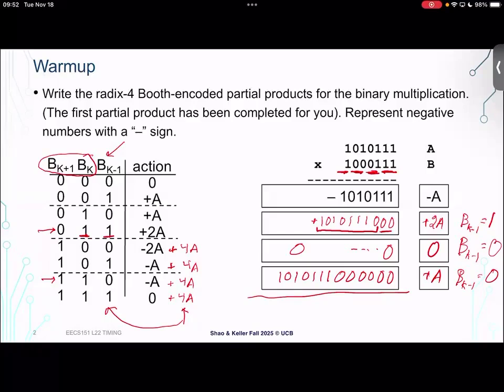And then if we're adding 2A, that's equivalent to A shifted left by 1 place. That's why 2s and 4s are very nice when we're doing binary operations, because as we've seen in this exercise, multiplication is expensive, right? If we wanted to do 3A, that would be expensive. That would be complicated. But if we want to do 2A or 4A, we're done.